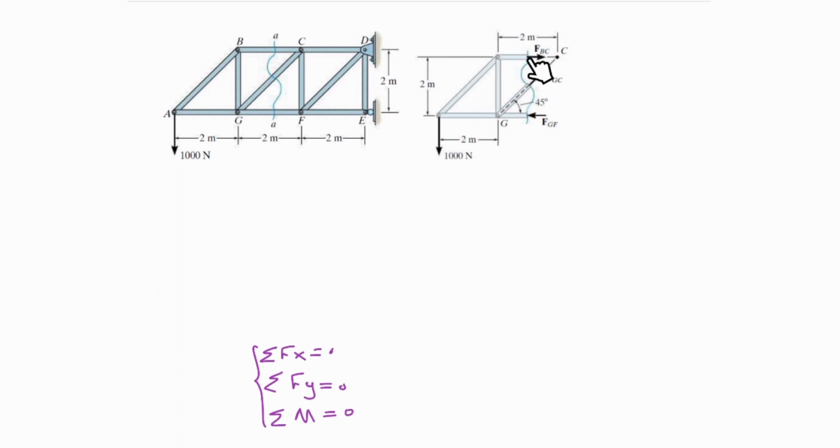And by finding these unknowns, we can find some other unknowns as well. For example, if you are here, by doing this you can find two unknowns, and then you can get back to the joint approach which was presented in the previous video and find these two. After doing the cuts you may use the joint approach for some parts like this, or like this.